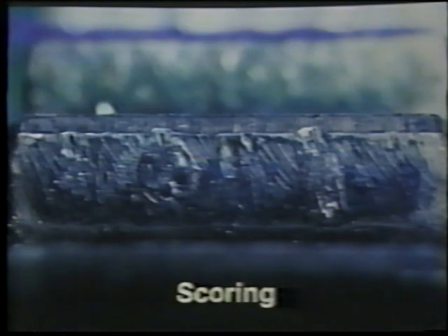Scoring, as shown here, is caused by high-temperature metal-to-metal contact resulting from insufficient oil film between mating teeth. The extreme heat causes an alternate welding and tearing of metal, which is rapidly worn away from the tooth surface. Replace. Burning is another problem resulting from extremely high operating temperatures.